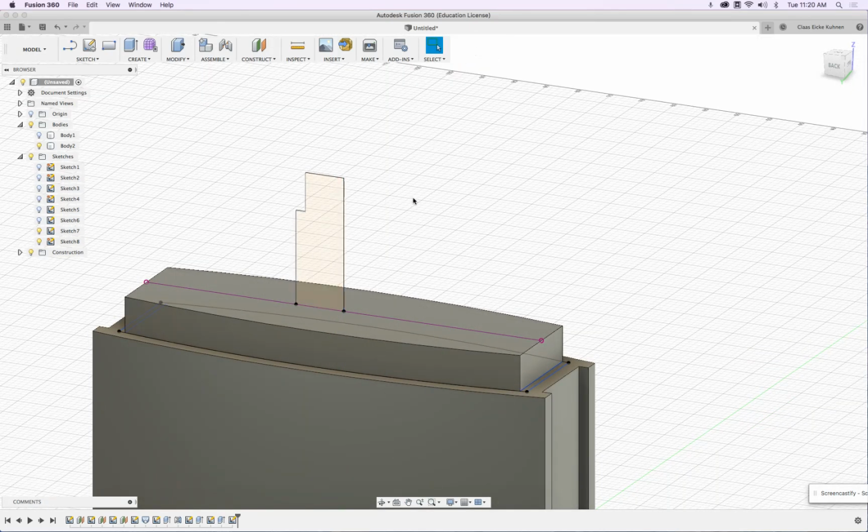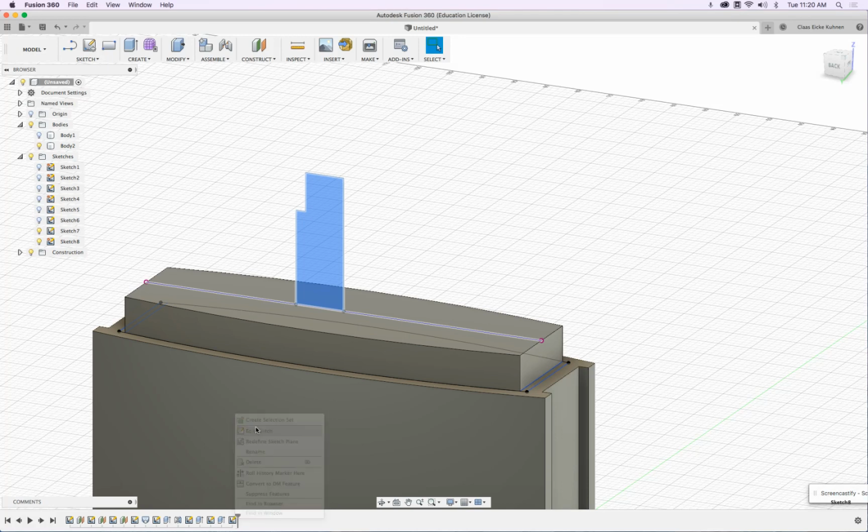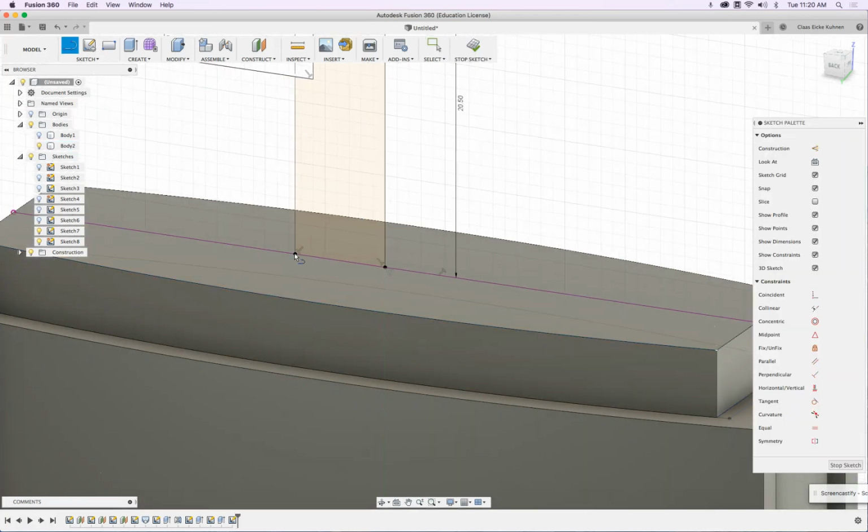Now this does actually an extrusion, a revolve, but I want to cut also into this body. So I could specify this inside the sketch already by adding another line below here. There. All these lines again, they are parallel. And then let's say this is actually 5 millimeters. Very good.